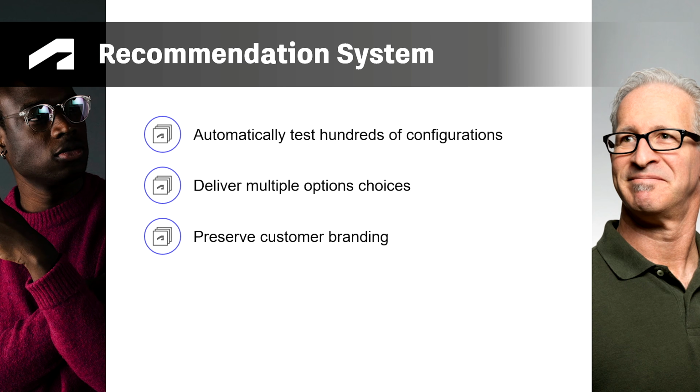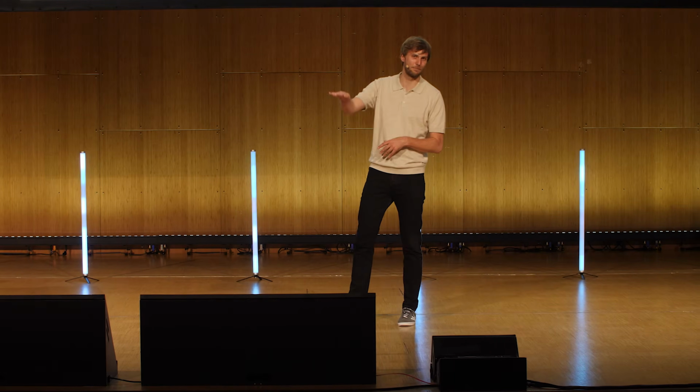And what we heard from all the customers when we started developing this is that if we generate surfaces, the quality of those generated surfaces needs to be high. And we need to stay, they called it customer branding. So a BMW should look like a BMW, an SUV should look like an SUV, and not mix up things, because that's the old story. If you run an optimization completely free of any shape, the perfect shape is a drop. Maybe if the optimizer is not well configured, you can also end up with a sheet of paper, but this is no longer a car. Usually you have some constraints also from a design side.